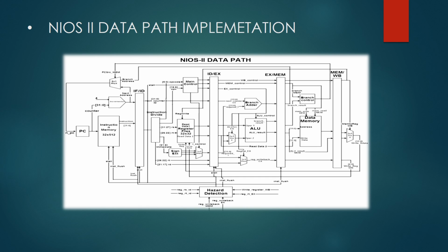The third stage is the execution stage, which generates the branch address, data memory address, results, and write back address. The read data 1 from the previous stage is fed to the ALU. The ALU either generates an address for data memory or a normal result. ALU gives out the branch result when comparison is done for branch output. It performs operations such as add, subtract, multiplication, comparison, and logical operations.